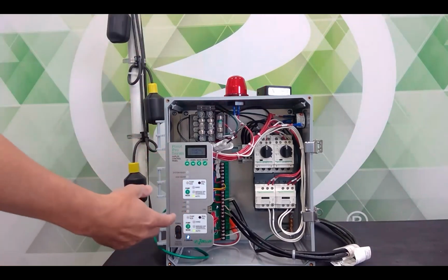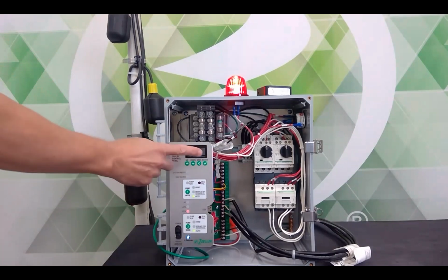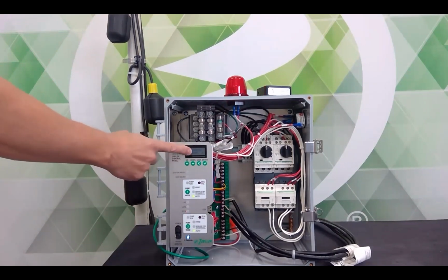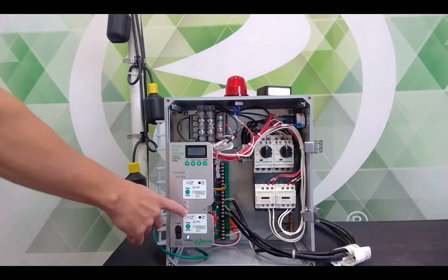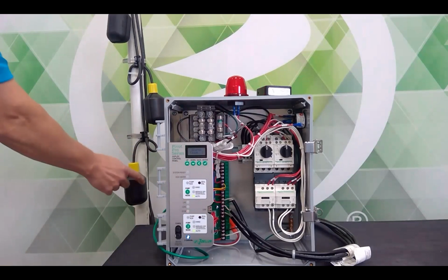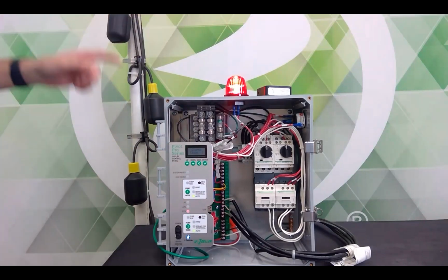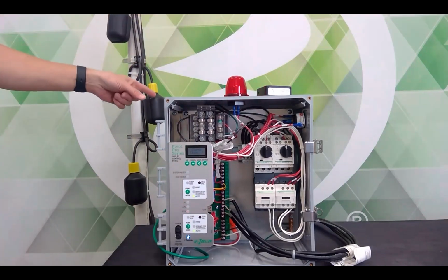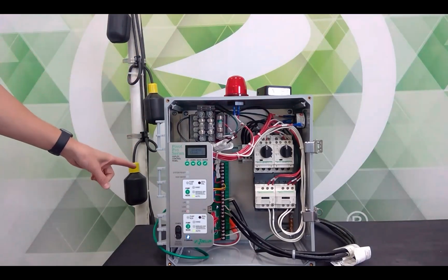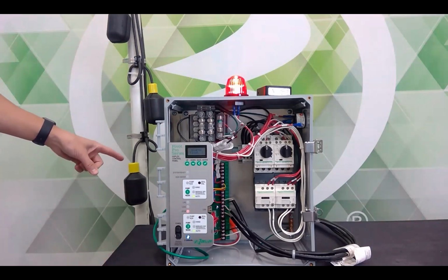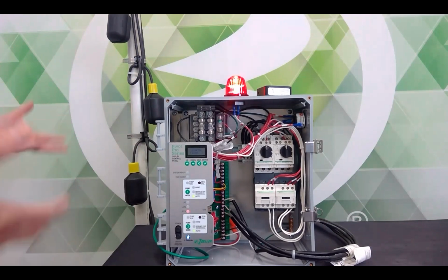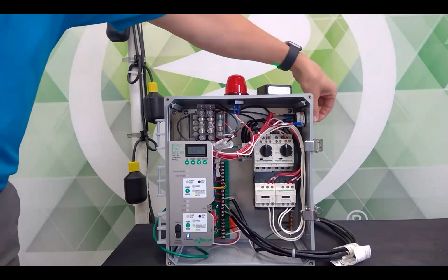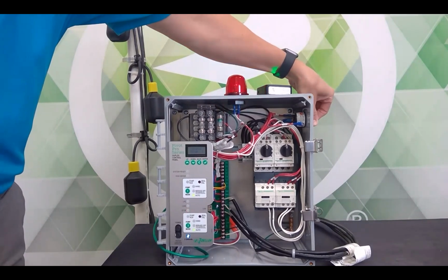But now later, somebody calls and says, hey, the alarm's going off. When I come and I open this door, I see float 1 is in fault. I see the LED on the stop float is blinking red. I know something happened with this float. But the point is, I prioritize running pumps. I still had an input. I know I can turn a pump on because this float came up. All those other control panels out there that we're all selling, there would have been a flood in this situation, or close to a flood anyway. All right, I'm going to reset it just by holding down the silence button.